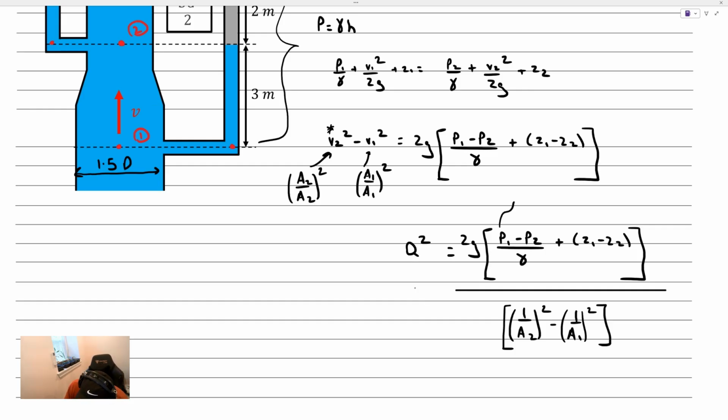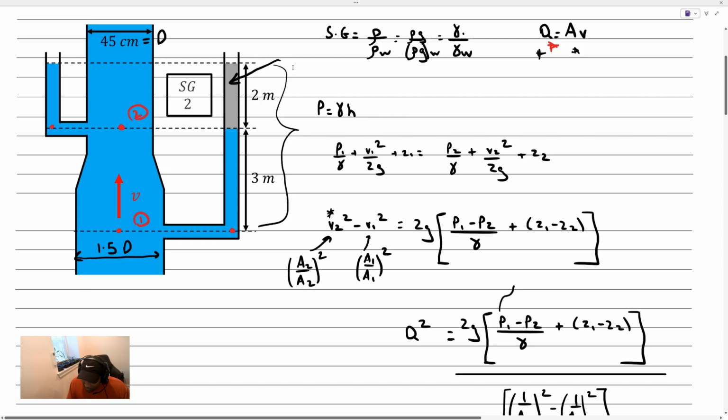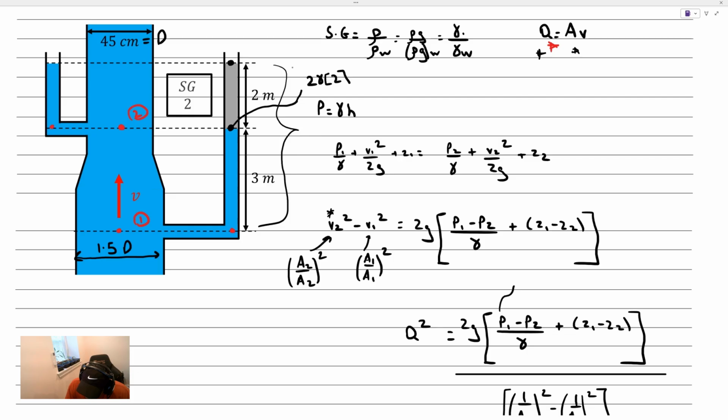What I know is that the pressure at 1 is given by rho g h, where for density, I have 2 different fluids here, right? If I start at this upper surface, which has a gauge pressure of 0, I descend inside of the fluid until I reach this second point where the fluid is going to change. The pressure at that point is equal to the density of that fluid. It's twice as dense as water multiplied by the depth that we went into that fluid. So the pressure right there is 4 gamma.